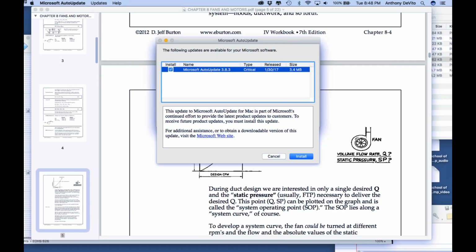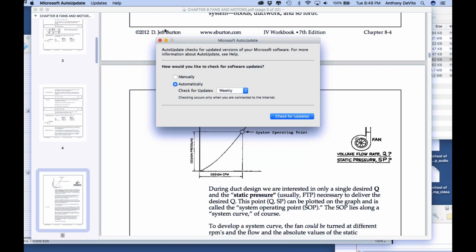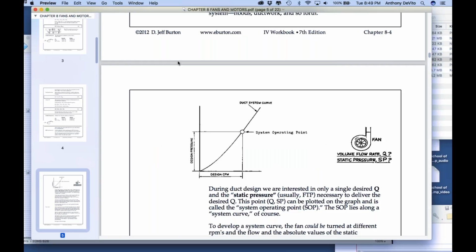Exactly. The whole thing is based on what velocity, what quantity of air you have to suck out at the hood, right, in order to contain the contaminant. So it's all designed around that hood and where that guy's working and what kind of material he's working with. So all of this is designed to accomplish that task. And all of the numbers that we're doing here to go through this design, the only reason we're going through all of this is because we have to decide how much our energy losses are going to be so that we can design this system so it actually delivers what we need.